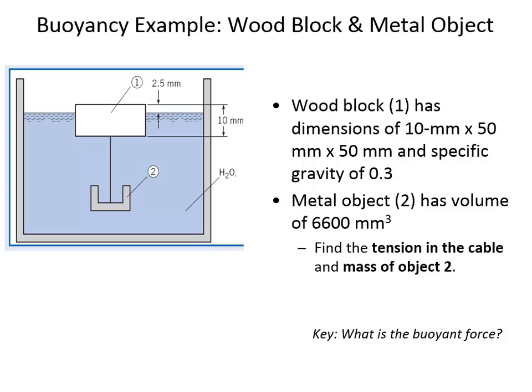So from that we'll get the volume in cubic meters, and we'll multiply it by the unit weight of the fluid. Even though it's made out of metal, it doesn't matter. The buoyant force just depends on the volume of water displaced and the unit weight of water. So that is 0.065 newtons. That is the buoyant force FB2.